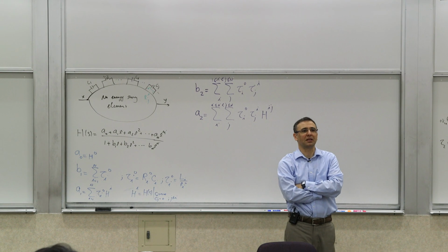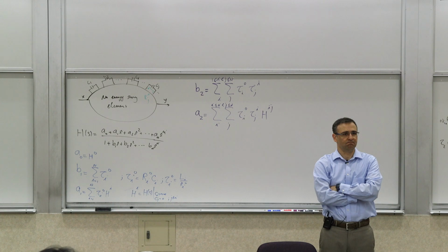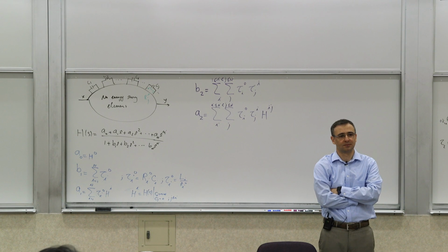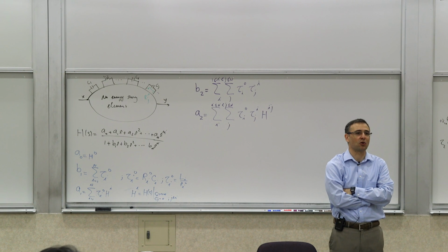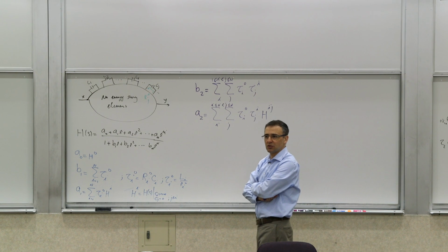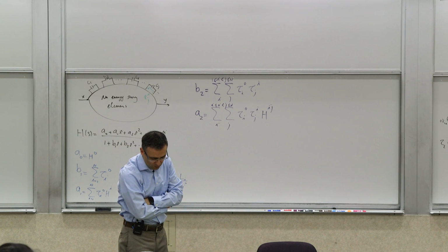What does hij mean? Both i and j are infinite valued. In this case, both capacitor Ci and capacitor Cj are shorted. And everything else that's not listed is open, or well, zero valued. If the capacitor is open, an inductor is short circuit, right?